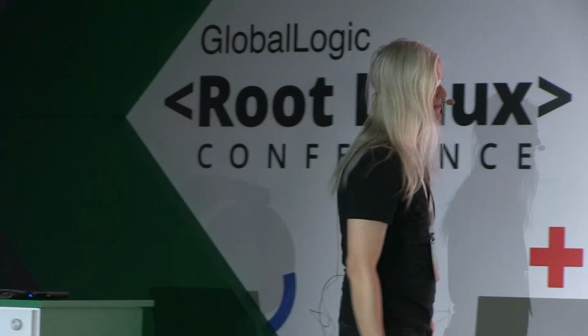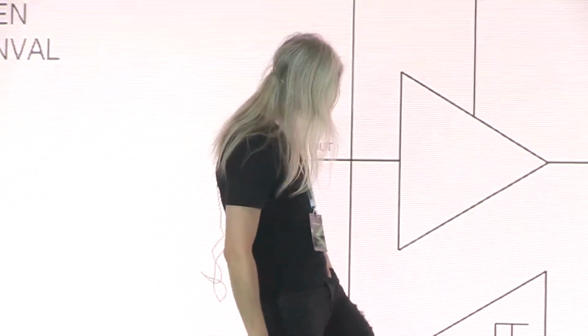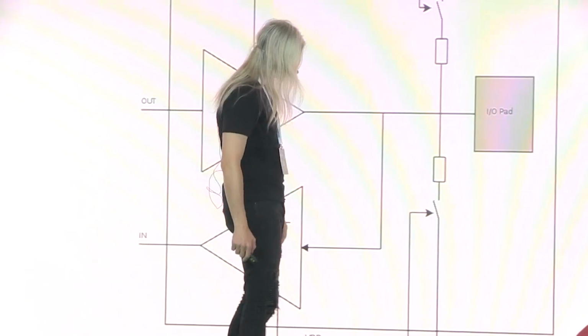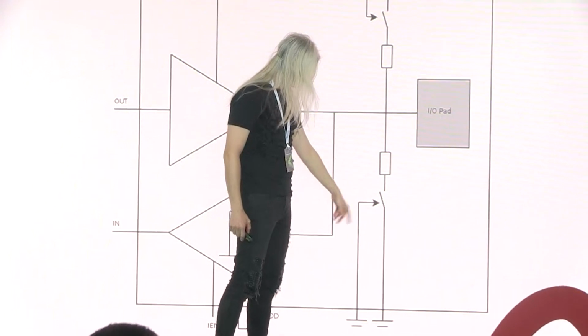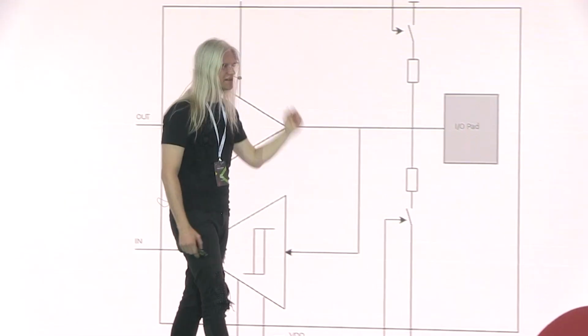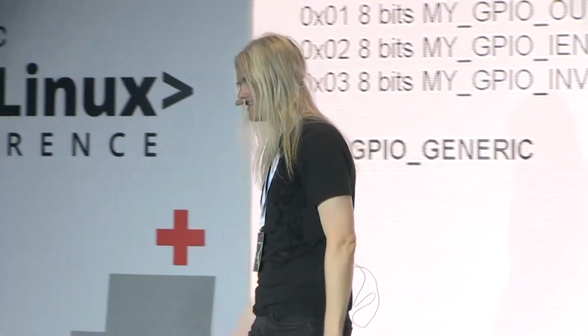You see that the ASIC engineer thought that this hysteresis control down here was really boring, so he just hard-coded it to VDD and turned it on by default, and then he thought that, yeah, this stuff we're not using, so let's just ground it so they are disabled, the pull-up and the pull-downs. If you want pull-up and pull-downs, you have to put them outside the package with a physical resistor.